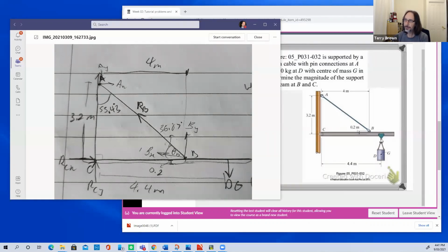So if this gantry is sitting on here, it's probably sitting on both sides. So there's two rollers on this side, two rollers on the other side. So in effect, this force that we've got here will be divided up between four rollers. So we'll have actually 4 point loads acting here. But in this case, we're just going to simplify it to one because that's all you can do.